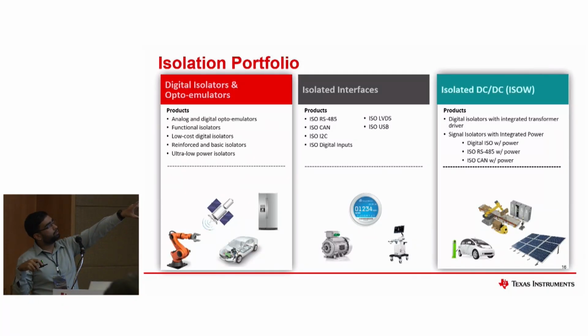Basically, it converts 24 volt inputs to the 5 volt domain. And we have one device to offer in ISO LVDS. It's a high speed differential part. And ISO USB has been our latest release in 2022, which is compliant to USB 2.0 with high speed compliance.